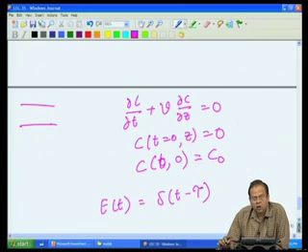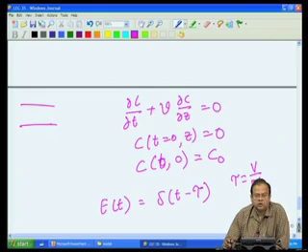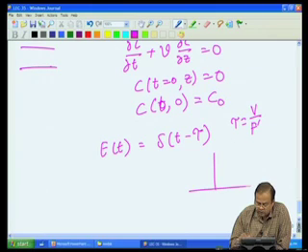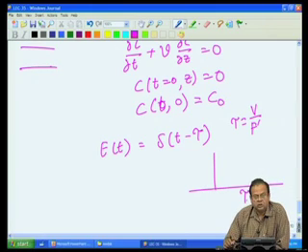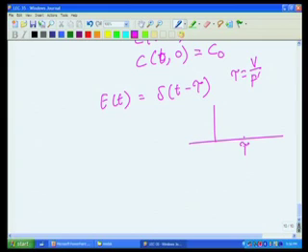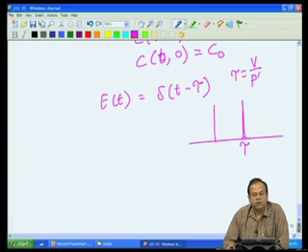once again, what is tau? Tau is my residence time, which I define as V by F prime. Whether it is a plug flow reactor or a stirred tank reactor, my definition of residence time is the same. So, what will I expect as an exit age distribution for a plug flow reactor? If I have residence time tau, then all the fluid elements come out exactly at that particular point.